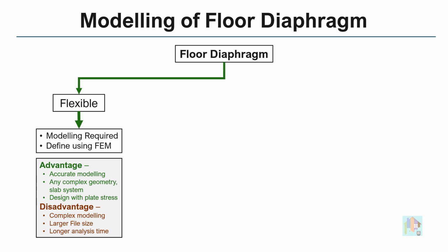One major disadvantage: modeling a plate mesh is quite challenging. We must generate it correctly considering all boundary condition and connectivity. Also, it increases the analysis time and model size.